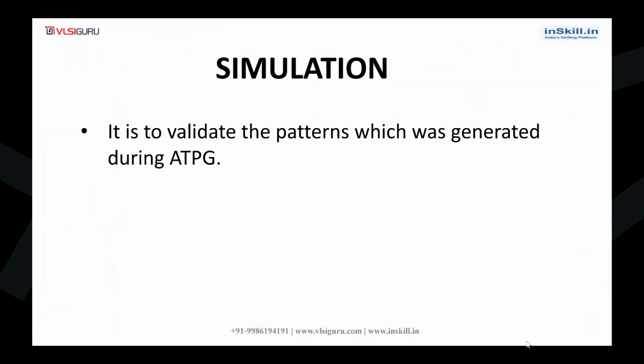simulations. Simulation is actually to validate the patterns which were generated during ATPG. Before we deliver the patterns to test the chip after manufacturing, we need to validate once whether proper patterns are generated or not. That is what we are validating with the help of simulations.